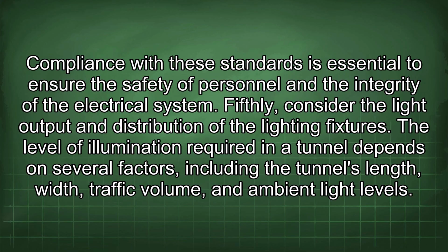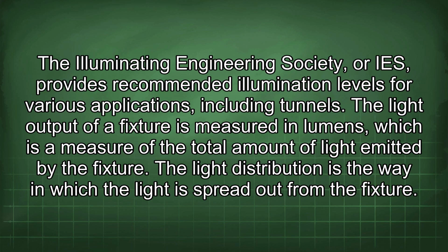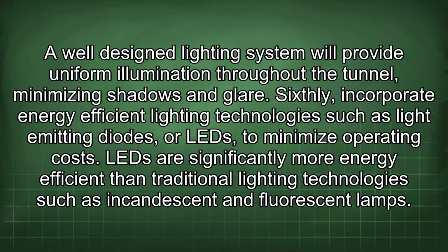Fifthly, consider the light output and distribution of the lighting fixtures. The level of illumination required in a tunnel depends on several factors, including the tunnel's length, width, traffic volume, and ambient light levels. The Illuminating Engineering Society, or IES, provides recommended illumination levels for various applications, including tunnels. The light output of a fixture is measured in lumens, which is a measure of the total amount of light emitted by the fixture. The light distribution is the way in which the light is spread out from the fixture. A well-designed lighting system will provide uniform illumination throughout the tunnel, minimizing shadows and glare.